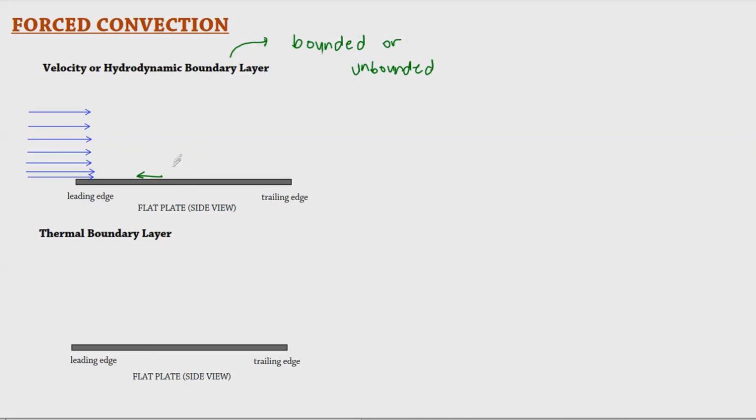Well, yes, that's true, but in essence, the truth is the flat plate actually exerts this resistance and somewhat retards this fluid layer near the flat plate or the boundary of this flat plate, and then the velocity of this streamline becomes 0. So it's like saying that the velocity of the fluid near the boundary, the flat plate, becomes zero as it comes closer to this boundary.